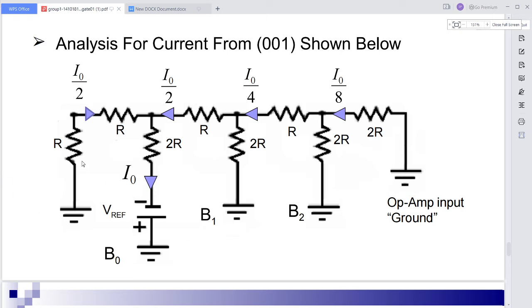See this one here, this 2R is in parallel, and so that, series connected, that is R. Like that, if you simplify from here onwards, you have to proceed with 2R and 2R in parallel, and this is in series, so you can get the R equivalent is R plus R is 2R, and again 2R is in parallel.